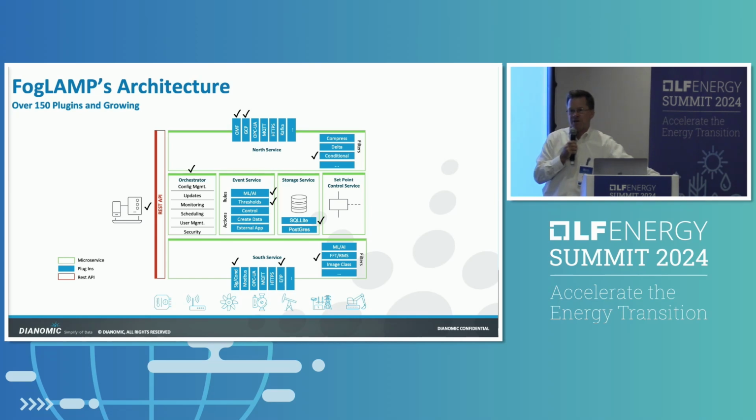A really cool use case we have going right now is, how many people have heard of SKF? Cool. So SKF, if you don't know it, they're a Swedish company. They're the largest supplier of ball bearings on planet Earth. And they have a service called Observer. So when you're a railroad company or whatever, you've bought their ball bearings, they'll do condition monitoring on lubrication and ball bearings. In paper mills, it's super important. So we've done several paper mill installations with them where we've integrated Observer. They're putting accelerometers out on these paper mills that are monitoring ball bearings, and then we integrated the PLCs of the paper mill. And so now we have PLC data, we have ball bearing health data through a REST API, and we've integrated that into the operational historian systems of the paper mill operators. And so it's the first time they got that exact same data. So that was all done through cloud.